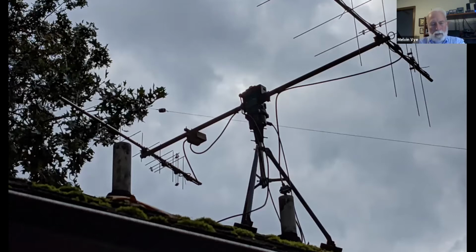And we know that for example, if you put up a vertical and you would say you have vertical polarization, and if you put up a horizontal dipole, you'd have horizontal polarization. But a third option is that the waves actually spin as they go off the antenna, and that results in circular polarization. Our satellites are not circularly polarized; they're linearly polarized with just a vertical antenna. But the reason that we use circular polarization is that the satellites are not stabilized. They're just kind of lobbing and floating around.